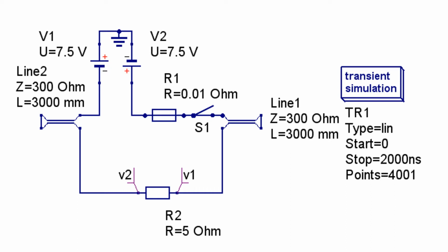The lines have a characteristic impedance given by the square root of L over C, where L and C are the inductance and capacitance per unit length. The characteristic impedance of the line gives the ratio of the voltage to current for traveling waves down the line.